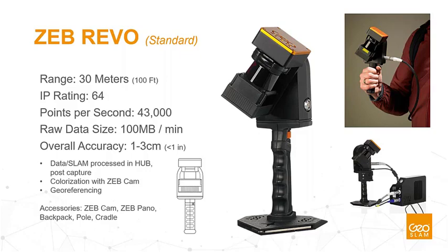We're able to use the base plate on the scanner that you see the scanner sitting on to do georeferencing by using the crosshair in there to obtain reference points as we scan, and you simply do that by setting the scanner down on top of a reference point. If you hold it still for a few seconds, it will automatically log that as a reference point, and then we can use that to georeference the point cloud. We can also extract geometric objects like spherical targets or building corners and things like that to be used for georeferencing or aligning our point cloud data with this.